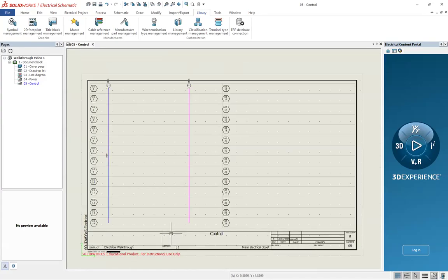So I thought I would start out with how to get the manufacturer's parts in here. Now, the way I have done it in the past is simply brute force in Google, right? Looking for things like Allen Bradley SolidWorks Electrical, or Siemens SolidWorks Electrical. I have done it that way, and it works. There are quite a few manufacturers who, if you get out there on their websites, you will find the zip files of part numbers that you can bring directly into SolidWorks Electrical.